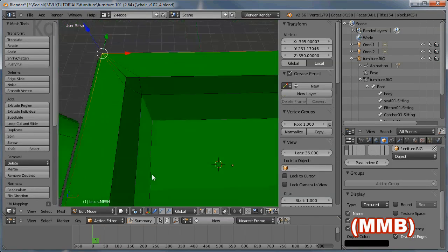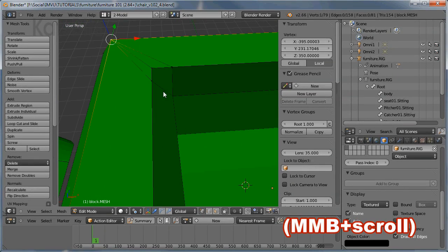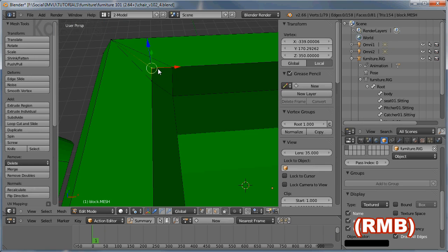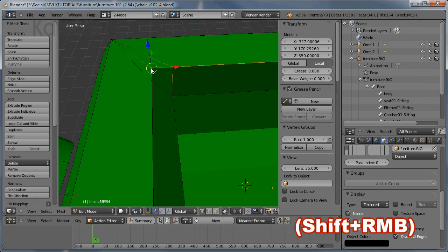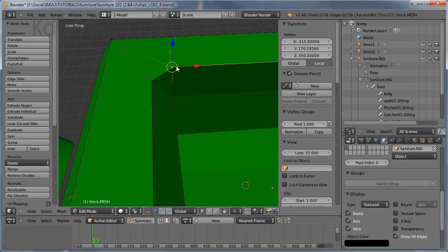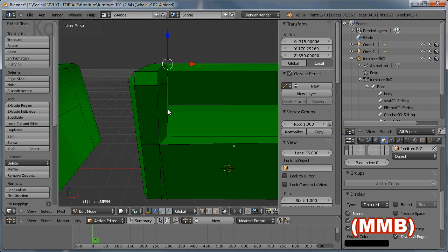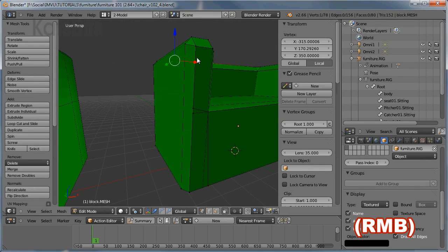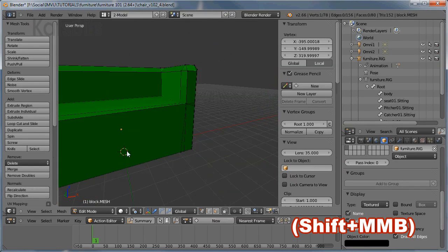Now it's important to note that with these corners, what we're trying to do is create a triangular surface here. That means removing this corner vertex. So select the vertex we want to collapse to first, and then the vertex we want to collapse to it second. And that creates our triangular surface. And then again, continue on around the mesh, removing vertices.